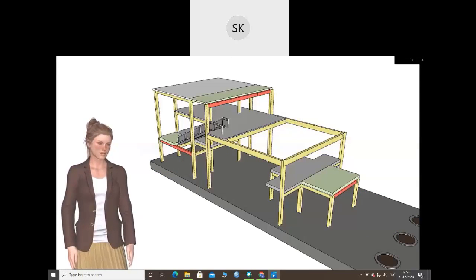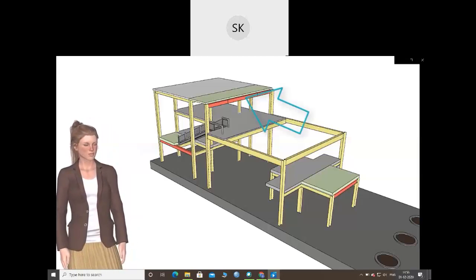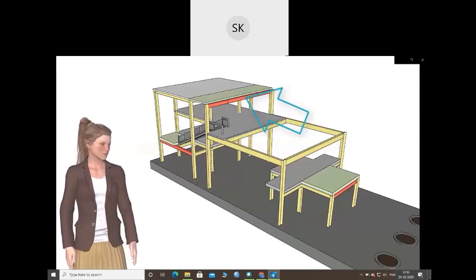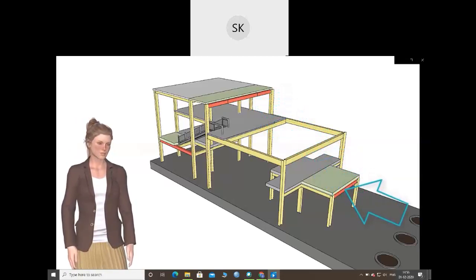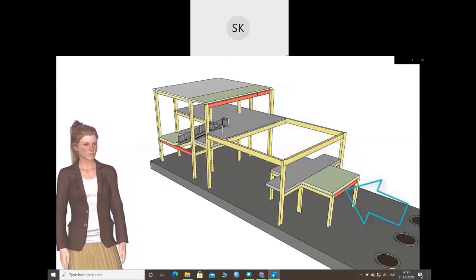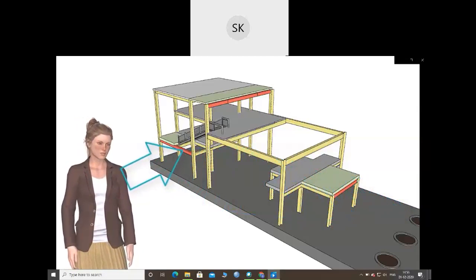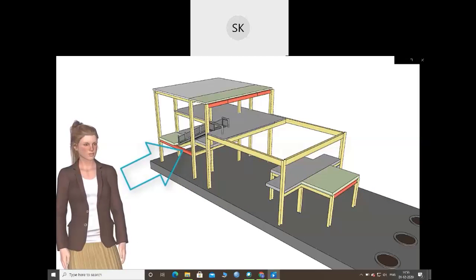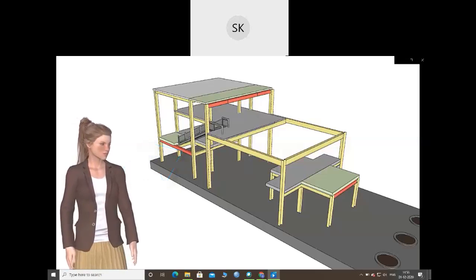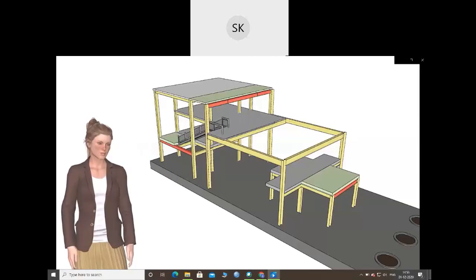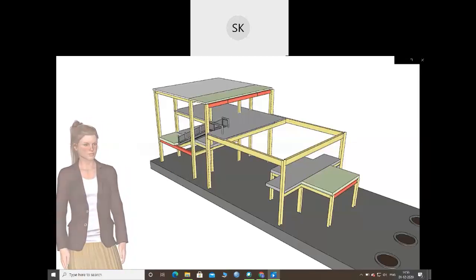We use the beam on the second floor to formulate the shear and moment equations due to concentrated loads only. For the short beam on the first floor, we end up writing the shear and moment equations due to a uniformly distributed load. And the beam on the side of the building covers the case of a partially distributed load combined with a concentrated load. In this presentation, we are going to assume that all 3 beams are simply supported.